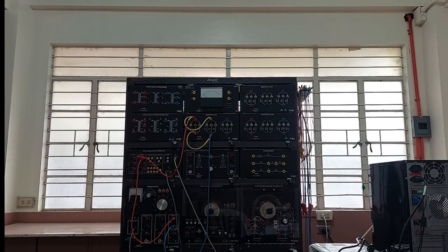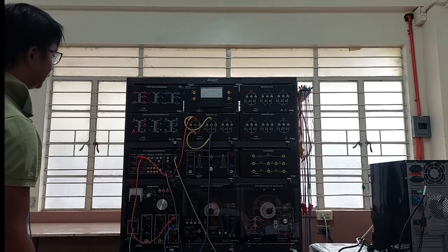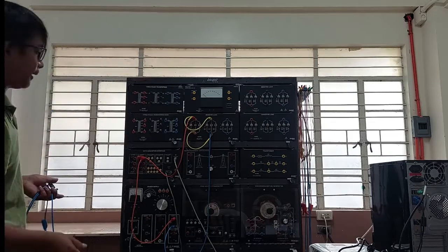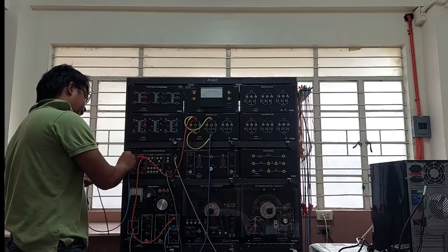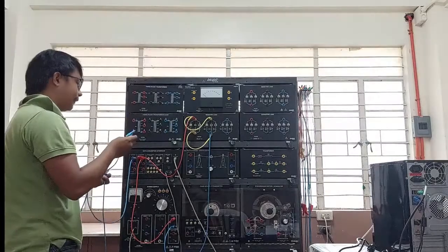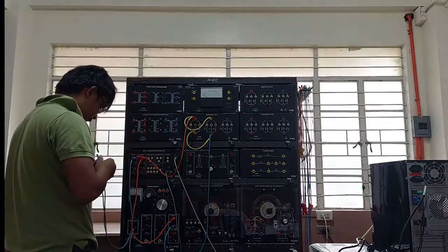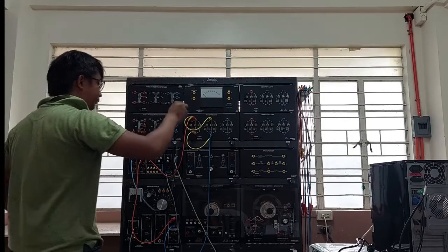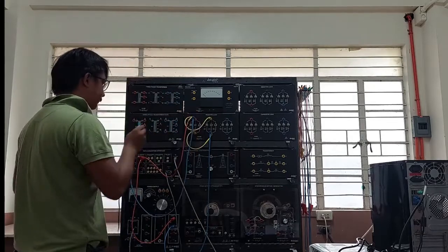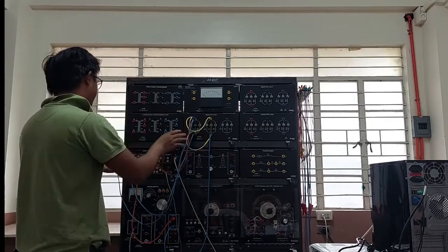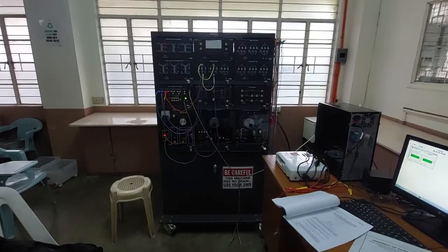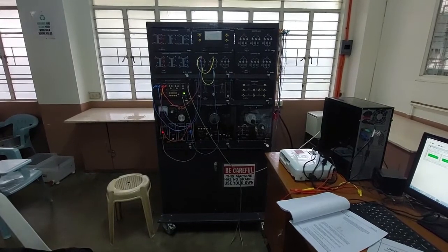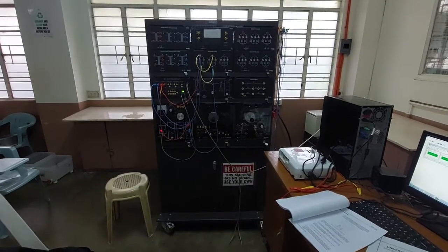So next is that we would measure the voltage of the resistor. So take note, naka-parallel yan. So tignan natin, parallel, from the positive of our voltmeter to the positive of the resistive load. Okay? Yan. And then from the negative of the resistive load to the negative of our voltmeter. So guys, after connecting the circuit, we are now ready to energize it.